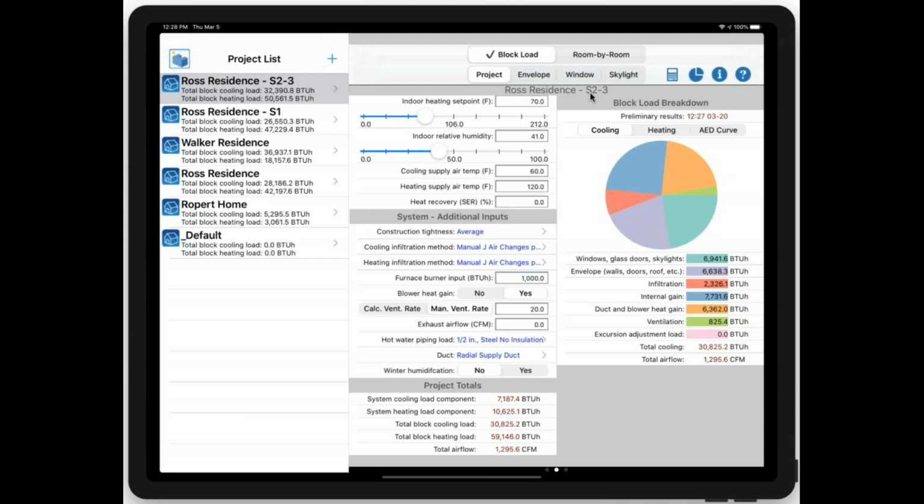Yeah. So where is it located? Is it in line with the furnace blower, or what's the setup of that? Most likely using a separate system, either an LG or a Zender. And so that's a balanced system, essentially. Yeah, I would enter the ventilation rate, and is it being conditioned in any way? Is it removing the humidity or adding humidity? Well, no, the ERV unit should maintain the humidity level. Yeah, maintain the humidity.